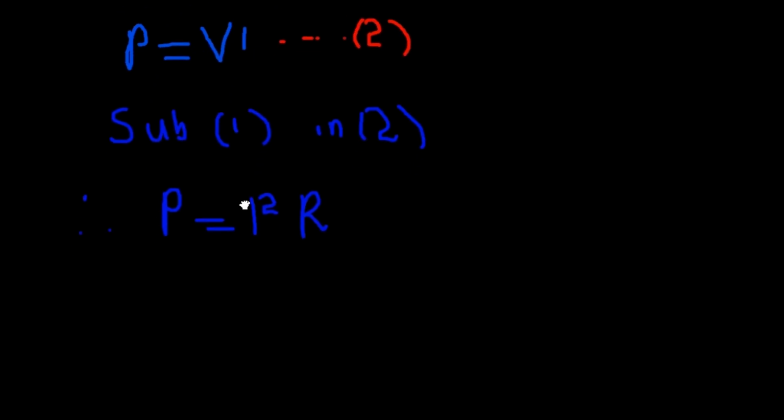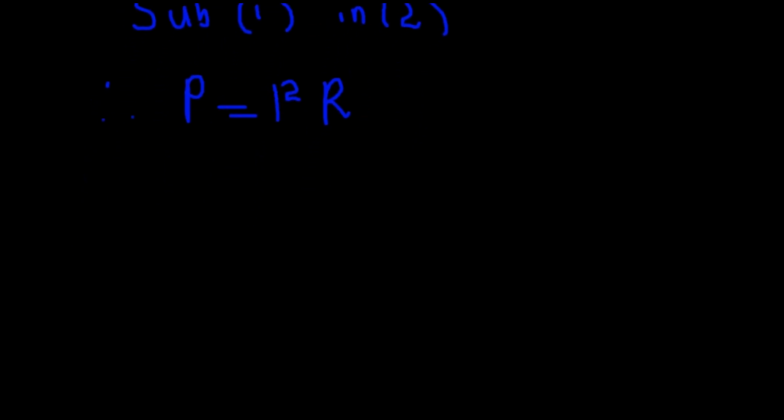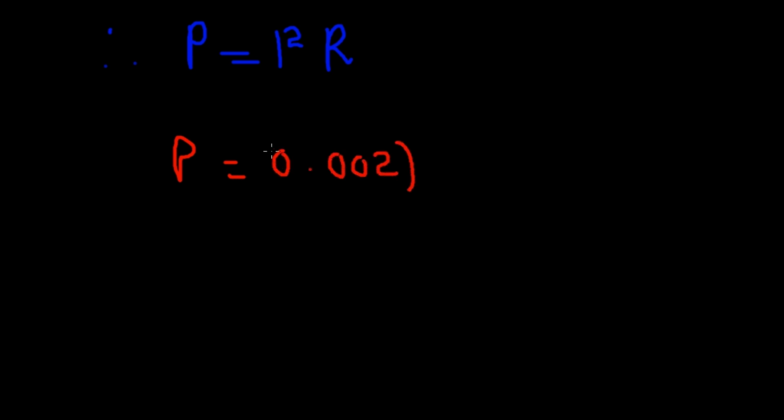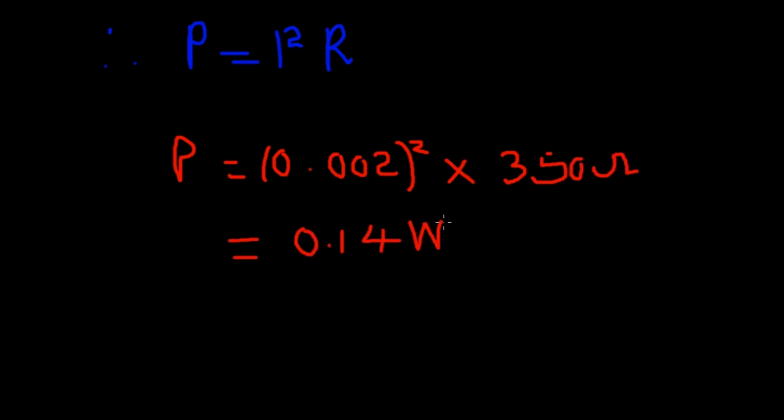Power rating of resistors. Another important aspect is the power rating of the resistor. If the resistor isn't rated for enough power, it could overheat and fail. We can calculate the power dissipated by the resistor using power, P, equals current squared times resistance, R. In our example, with 0.02 amps of current and a 350 ohm resistor, the power is P equals 0.02 squared times 350 equals 0.14 watts. So a 1/4 watt resistor would be more than enough here.